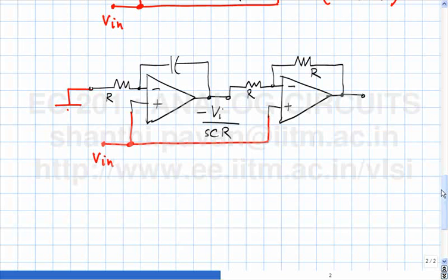We said that if you had an amplifier with a gain A of S, which is of the form 1 minus R by SL, then connecting a resistor between the input and output of the VCVS should give you an inductor looking in.